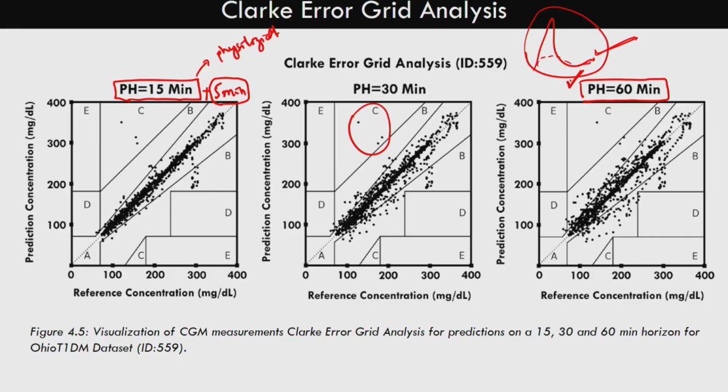Okay. So in sensor signals, generally, let's say we are taking sensor values every 5 minutes. What CGM sensors might be doing is they sample at a very high rate, and then every 5 minutes they average the data and give you an average value. So when you average out, this peak actually disappears. Yeah, makes sense.